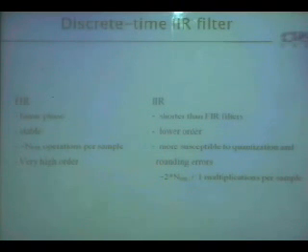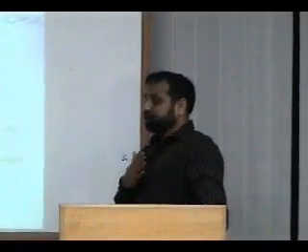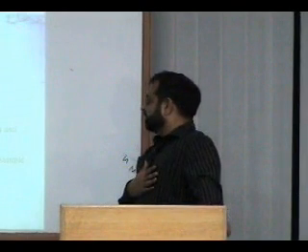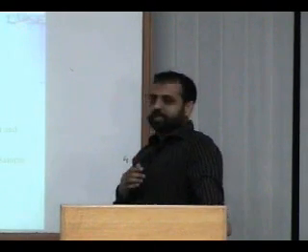It will be a very high order. So this is the price you pay. If you are designing an IIR filter, it will be shorter than what is guaranteed for an FIR filter. It will be very small, with fewer computations and lower order, but more susceptible to quantization.